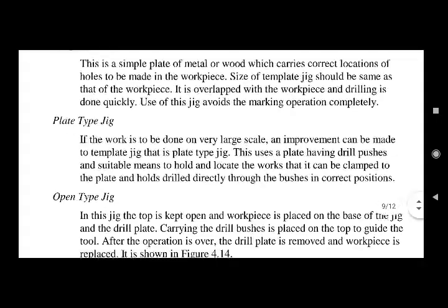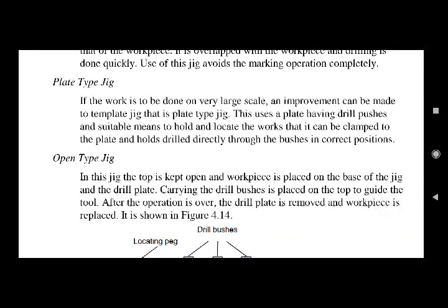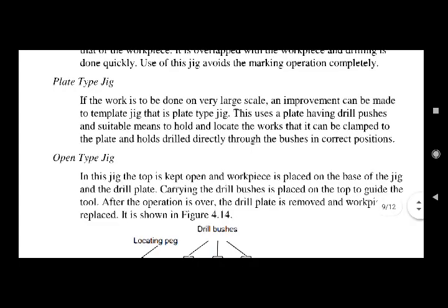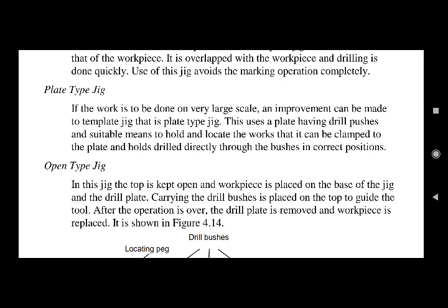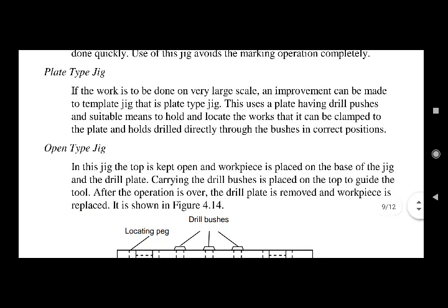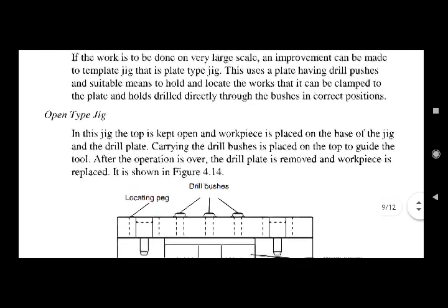Now the plate type jig. If the work is to be done on a very large scale, an improvement can be made to the template jig, that is a plate type jig. This uses a plate having drill bushes and suitable means to hold and locate the work so that it can be clamped to the plate and guides the drill directly through the bushes in correct positions.